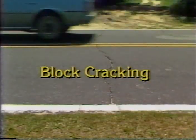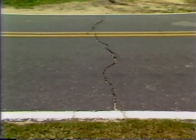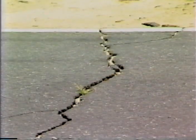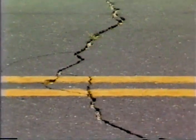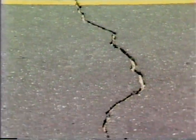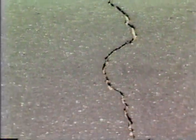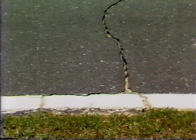Block cracking, also called shrinkage cracking, is a distress which often warrants crack sealing. Daily temperature changes cause expansion and contraction in the pavement. As the pavement ages and hardens, it is less able to withstand this stress. It pulls apart, creating block cracks.